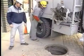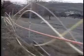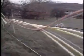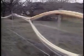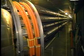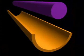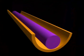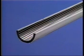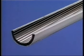Pulling cable through long sections of underground duct will require mechanical pulling equipment and lubrication. Curves, turns, and undulations in duct placement will determine the amount of friction encountered during the pull. It is important to use the correct duct type for your application. Corrugated duct is flexible but would offer too much friction for long pulls. In smooth wall duct, a large surface area of cable jacket contacts the duct wall, resulting in high friction. Rib ducts reduce this surface contact area to a series of edges, significantly reducing friction.